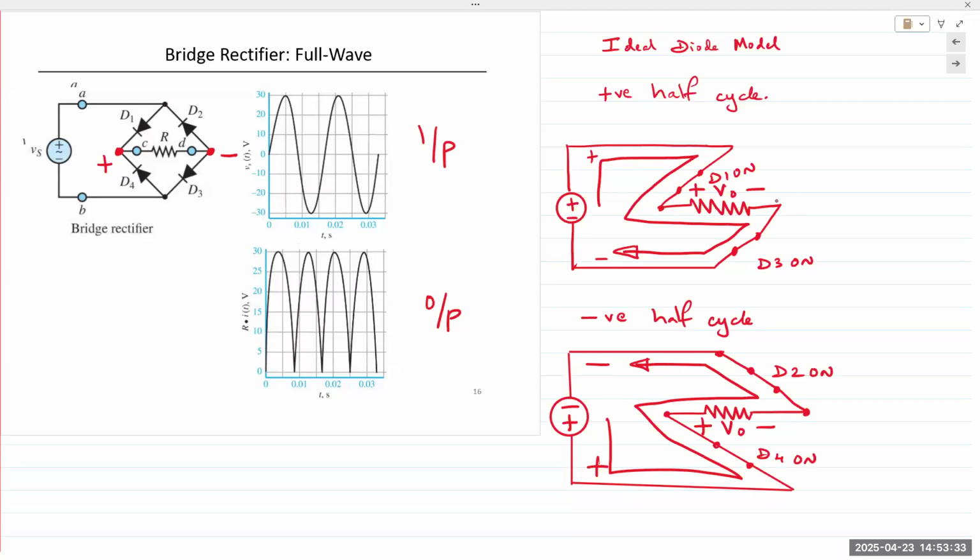Modern chargers first have a diode. They rectify the high voltage 110 volts AC into a pulsating DC, give it to a capacitor, a high voltage capacitor that filters it out, and then it's fed into a transistor oscillator. So it creates a high frequency AC signal. And again, it's just laws of physics: if the frequency is high, the transformer will be small.